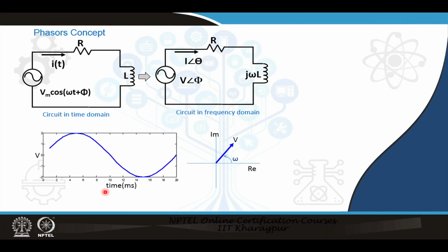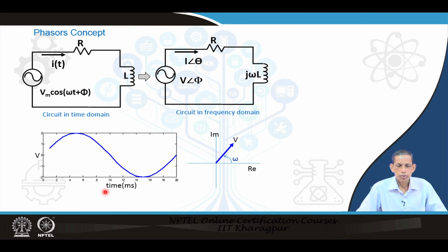We know phasors, we have dealt with these in all the relays. We started with phasor estimation, and then based on the phasor estimation, the phasors, voltage, currents, and then went for the sequence components which are being widely used for different protection applications, directional relay, differential relay, distance relay, and so on.